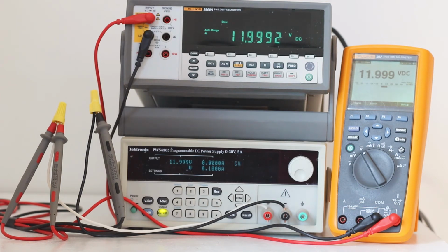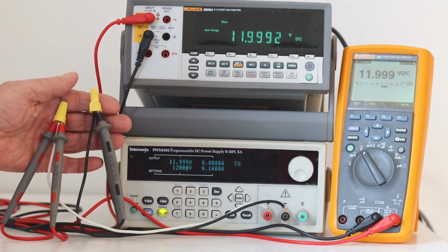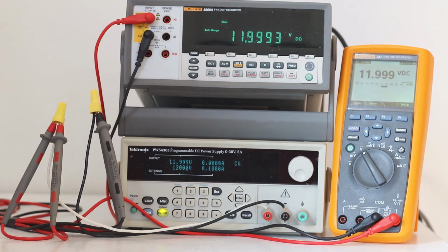To illustrate, let's do some measurements with real-world electronic instruments. Here is a good way to connect meter probes, especially when there are 2 or more conductors that have to go together. Solderless connectors, so-called wire nuts, work well because then you don't have everything jumping around.